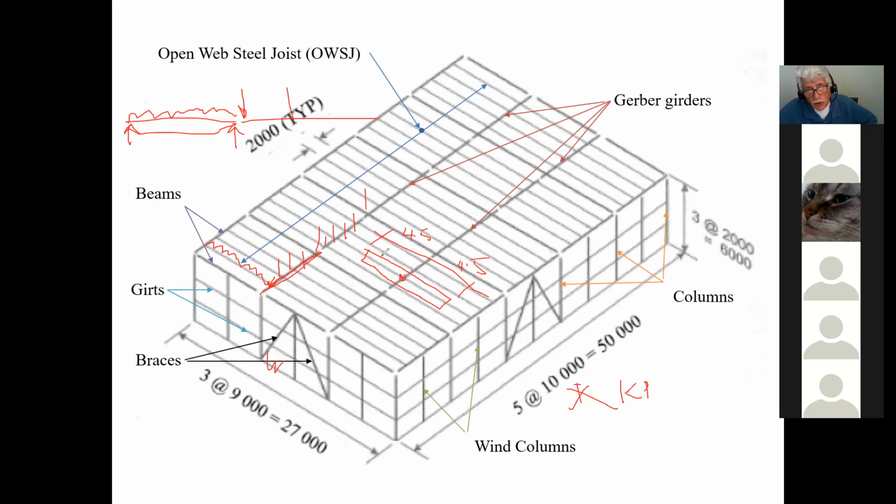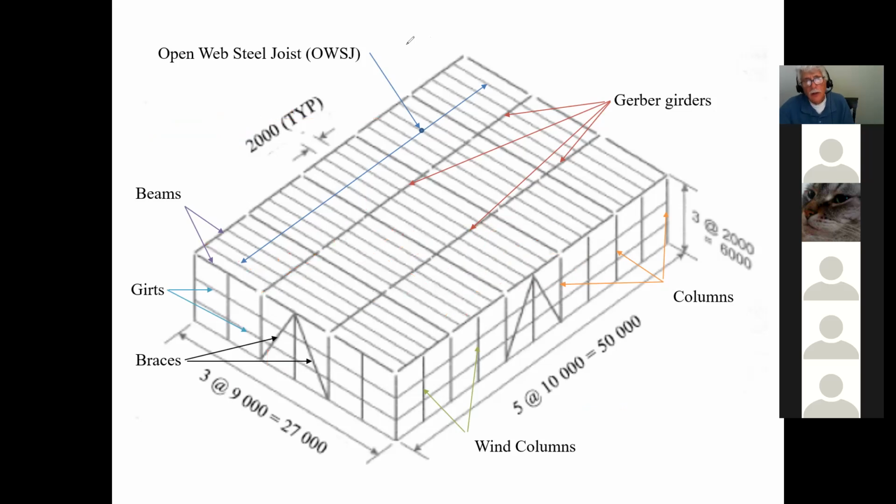So that's the dimension of all the load here. And then in this direction, of course, is the spacing of my joist. This is 2 meters. So the tributary area of all that load coming here is going to be equivalent to 9 meters by 2 meters. And that's the tributary area that's contributing to that concentrated load at every place where the joist is supported by the girder. I just want you to see that and understand that.